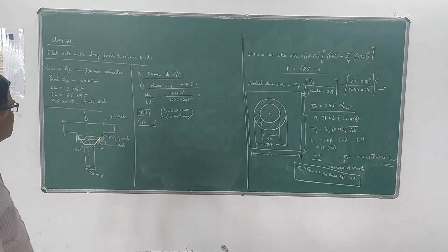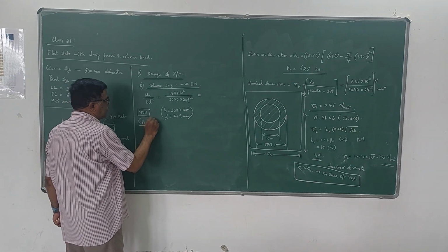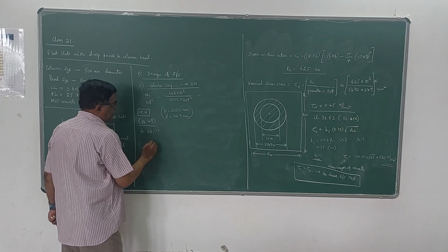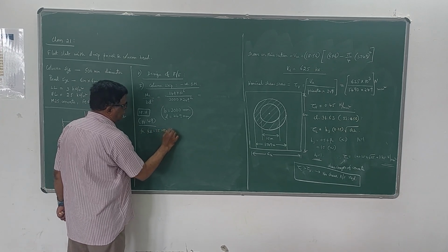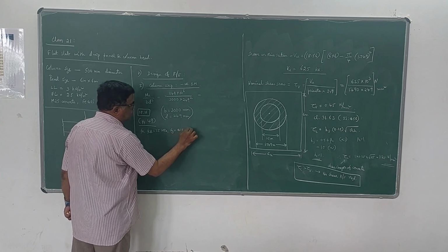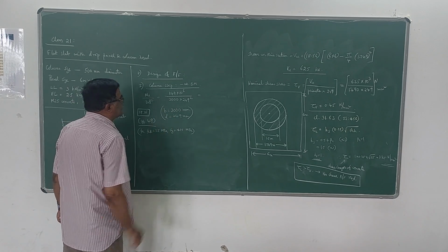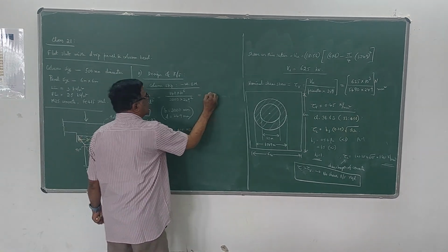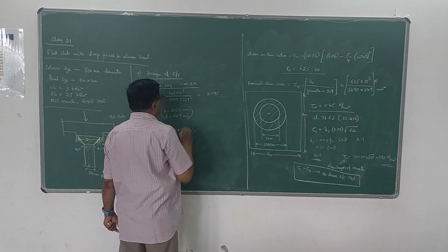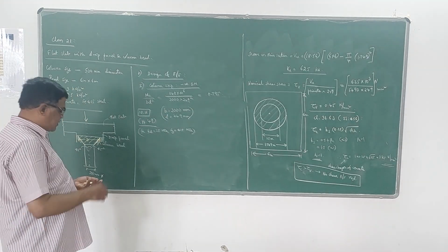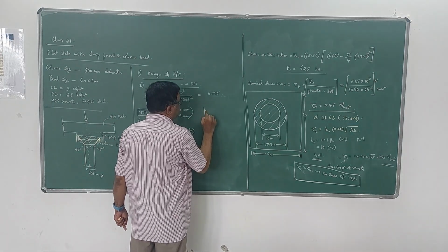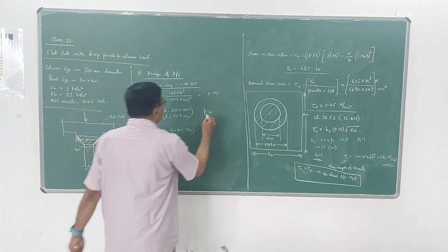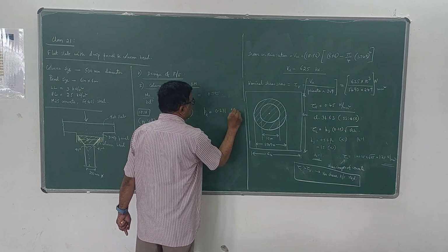Page number is 49, for fck 25 and fy. For these two, we have to see what decimal you will get: 0.795. From the table given on page 49 of SP16, we directly read out that pt value. If you don't get it, you have to interpolate approximately. It is 0.231 percent. So this is the percentage of steel required.